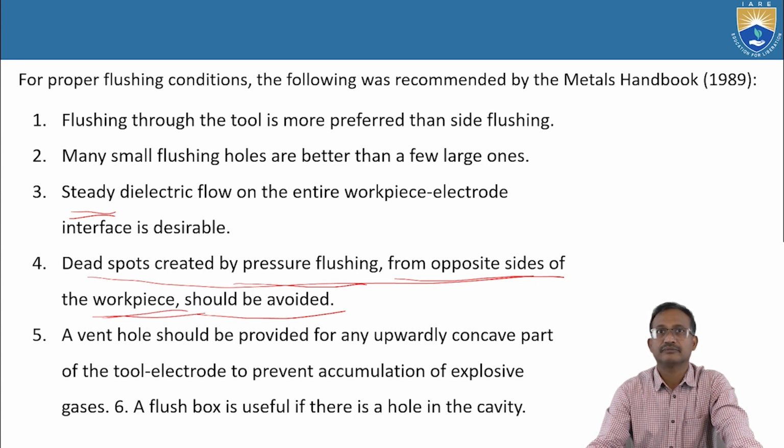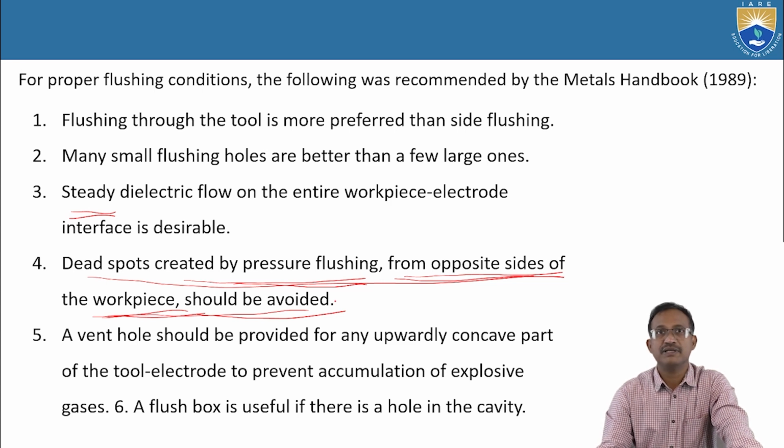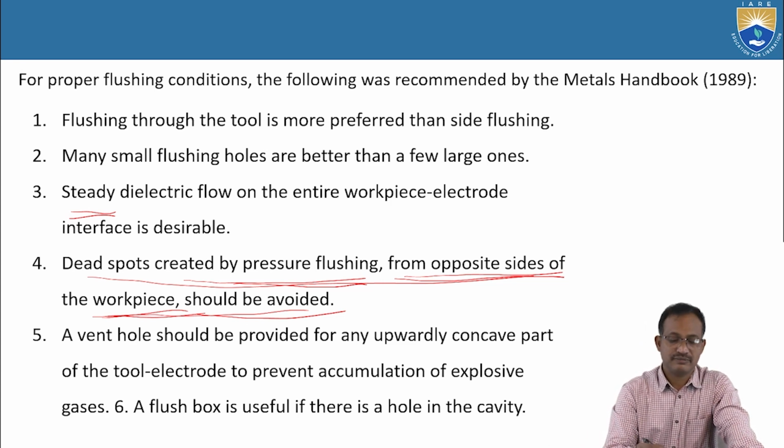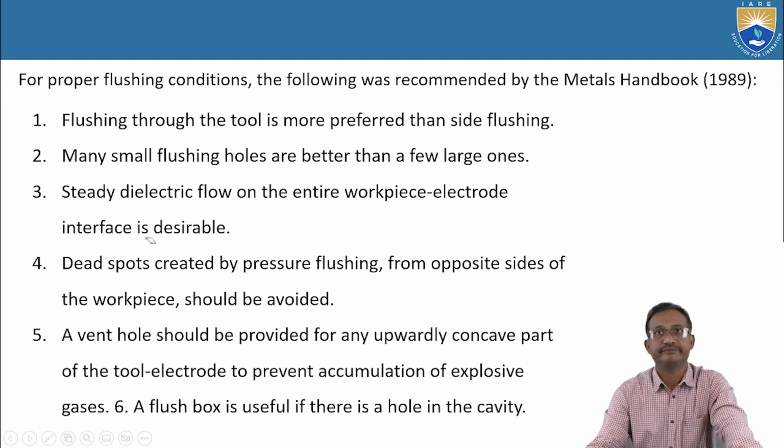Understood? Dead spots created by pressure flushing from opposite sides of the workpiece should be avoided. It means same sides should be preferred for the flushing.